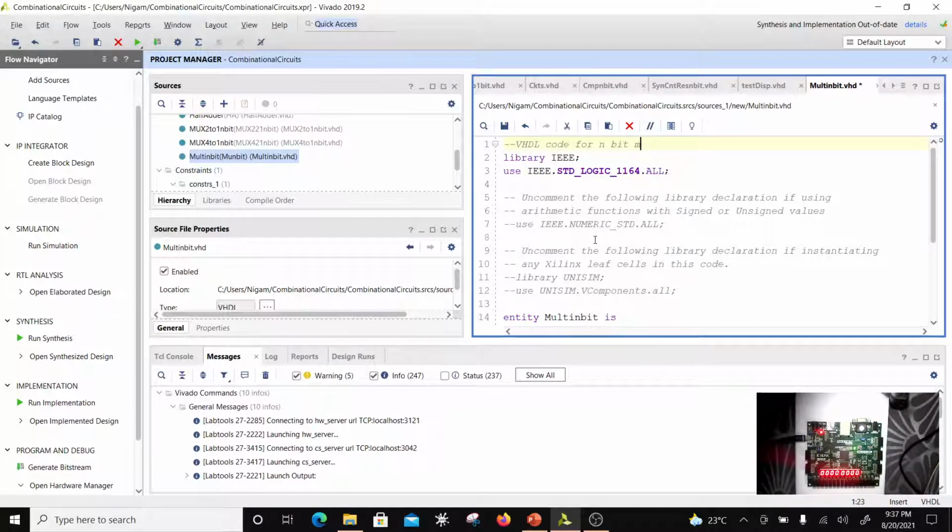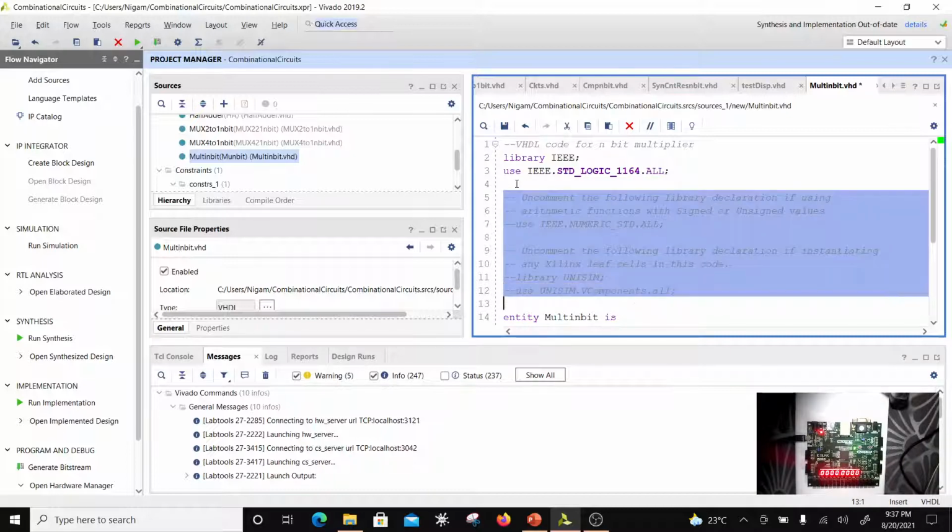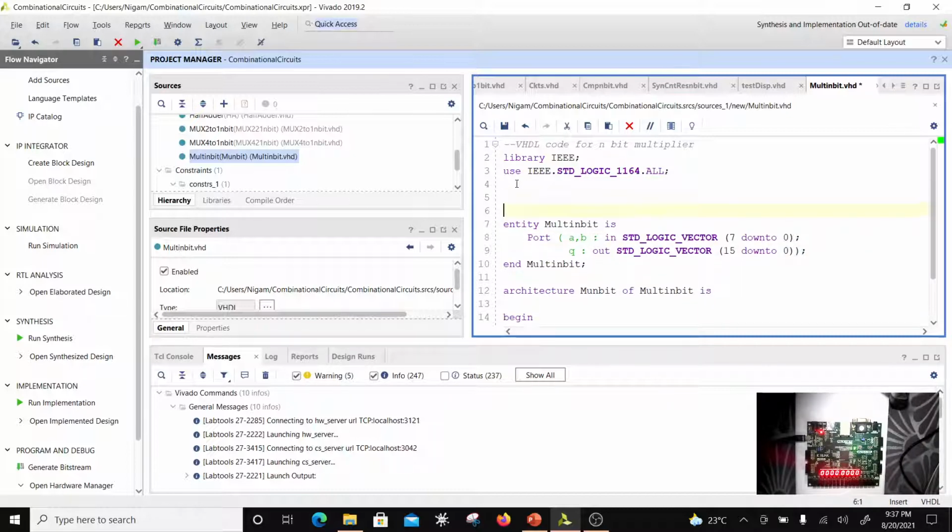So you see what is the benefit of keeping generic? The benefit is, if I'm designing a data path and I have a multiplier, I can fix the width of the multiplier to be the width of the data path. So with just one n, I don't have to redesign it. I can just scale the data path by any number of bits I want. So that's how scalable designs work.